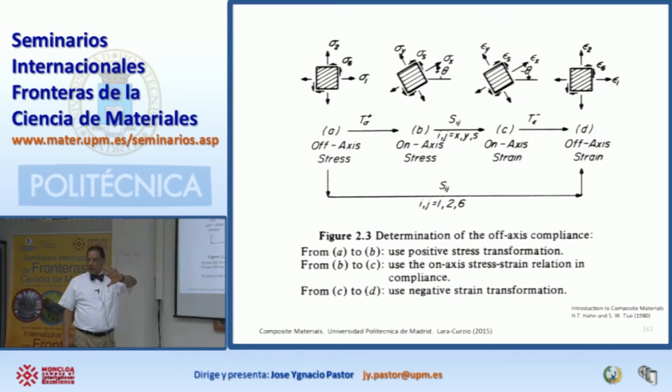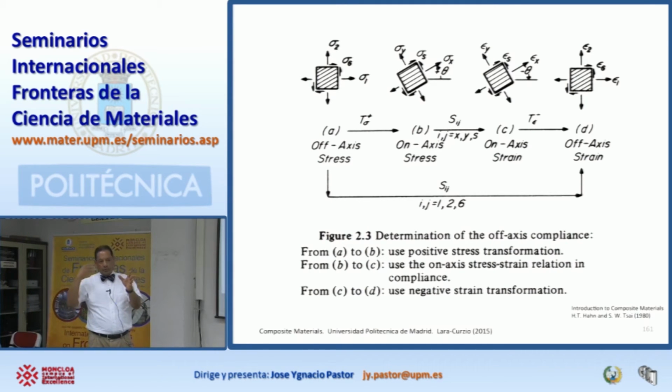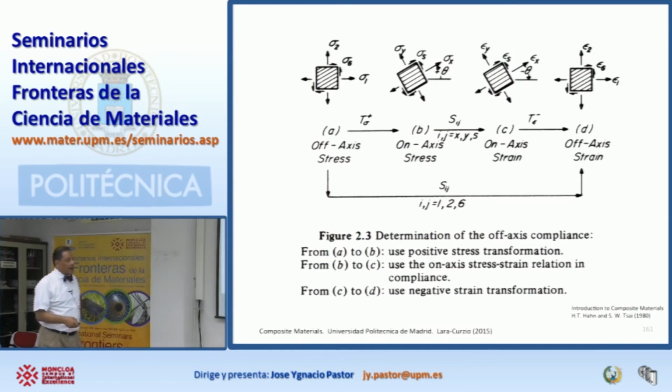I rotate 20 degrees, are my stresses lower or greater? If I go 90 degrees, I might have some bending, and the bending is really going to kill me, so I got to put more fibers in the zero direction to prevent so much deflection as a result of bending. And that's what happens. This is how these structures get designed.